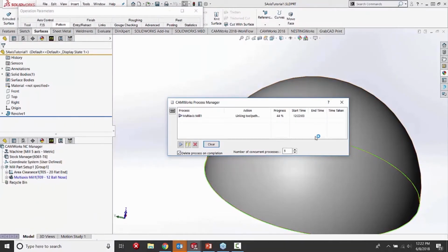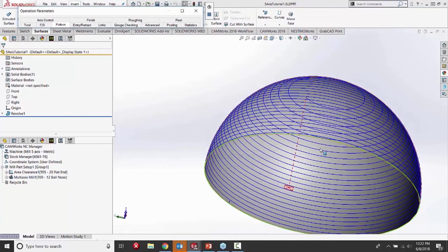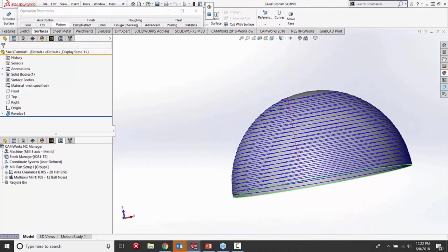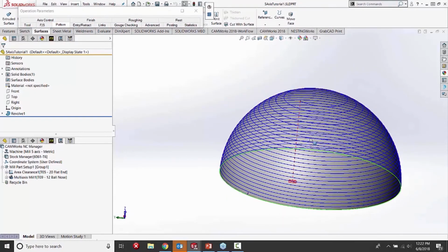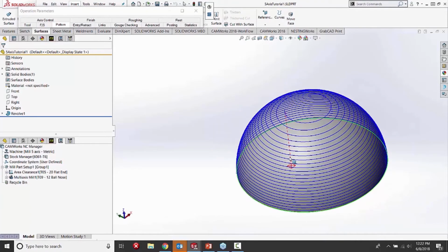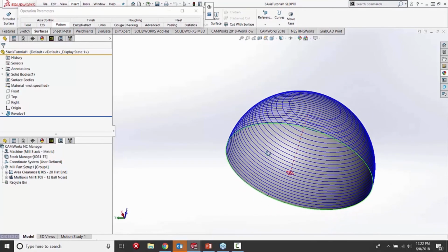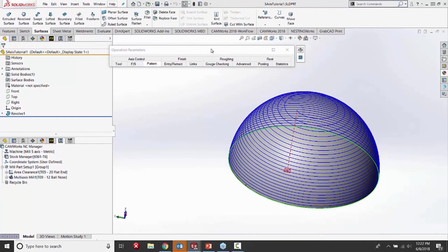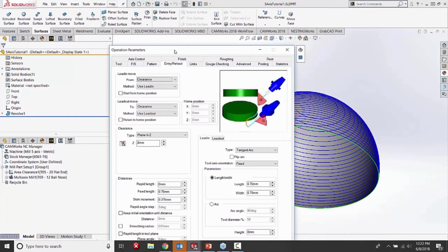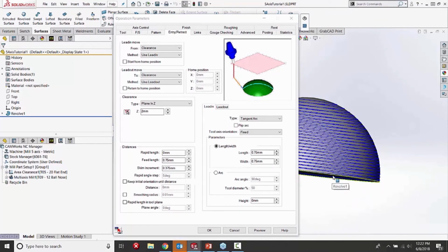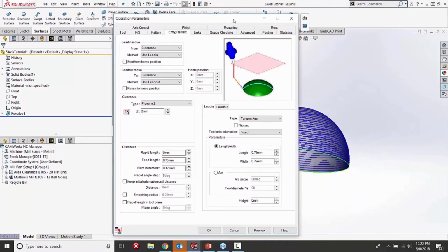And I really get what I was looking for earlier, which is the tool staying on the surface and keeping a continuous cut going. There are no more excessive lift-offs, coming off and leading in and leading out, back off the part, back onto the part. So staying continuous, staying on the surface. My only issue now, that last bullet point I mentioned, we want to jump into the entry retract tab. And right now our clearance plane is 2 millimeters from our origin in Z, which is not enough to make it out of this part.